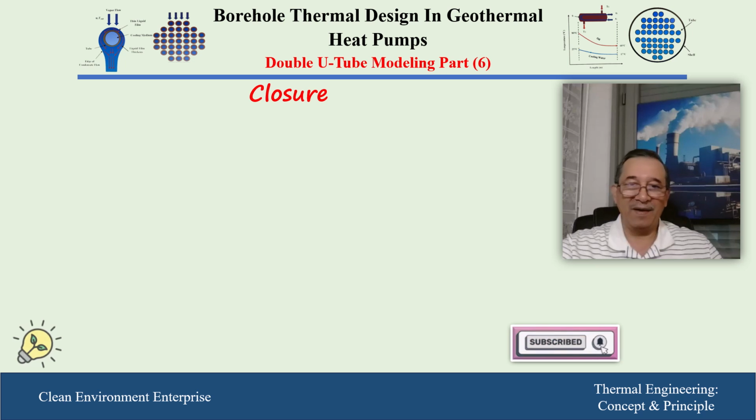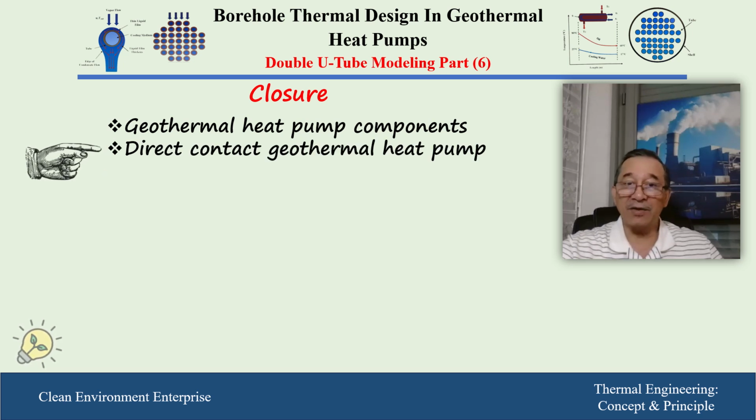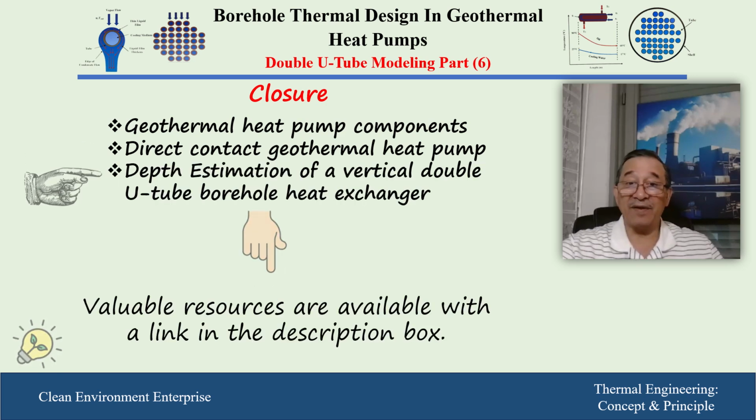Then the closure of the present video and its content: we have passed through the geothermal heat pump components, and we described the direct contact geothermal heat pump, where we have a heat exchanger that is composed of a double U-tube that is installed vertically in the heat exchanger, and we have presented one of my correlations which has been published in the literature, and we have some references you may find in the description box as a list.